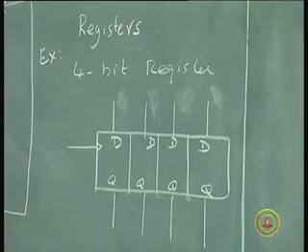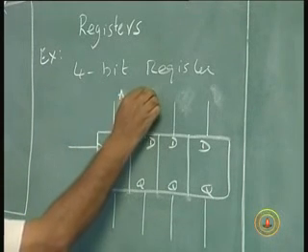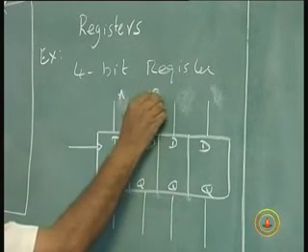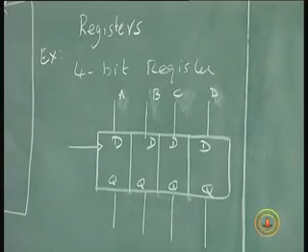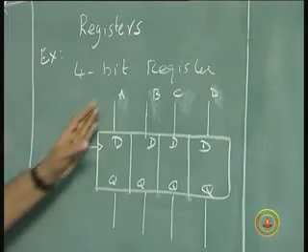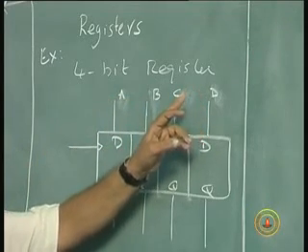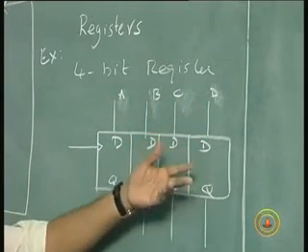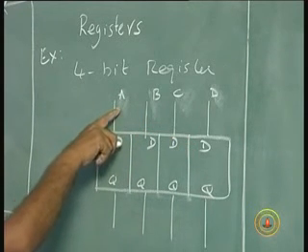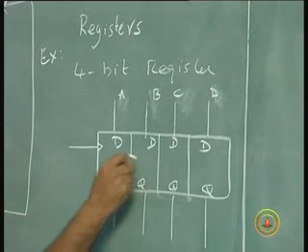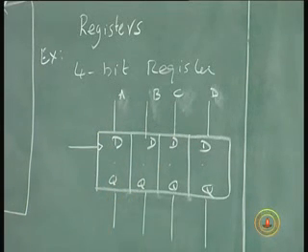So I can put any data here. Or you want to put it the A, B, C, we have been using A as the most significant bit and D as the least significant bit. So when you put this data, A should be the most significant bit. And that's okay. We can just use this way. Now I can put this information and clock it. It will remain constant. It will remain inside and also be available here. When I want it, I can read it off.